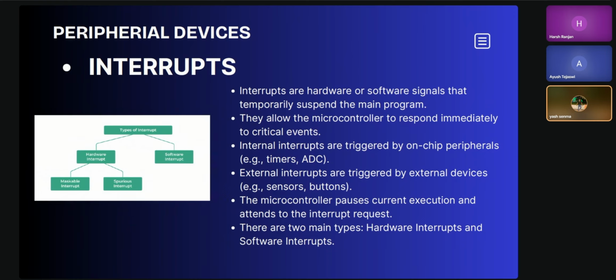For example, pressing the start button triggers an interrupt and begins washing immediately. If stop is pressed, an interrupt driven handler halts the operation. We configured the INT0 pin for external input and wrote an ISR for it.